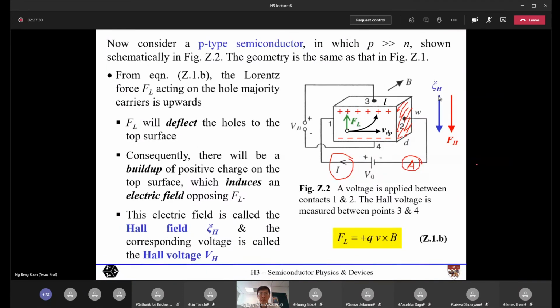Just to follow up on his question, when you say you take the current divided by the area, doesn't that give you total J instead of JP drift? Yes, it does. Wouldn't the issue be that there will be some discrepancy between J total and JP drift because you don't take into account the electrons? Generally speaking, if your p-type doping is sufficiently high, you'll find that the minority carrier drift current will be negligible. So it's okay to ignore.